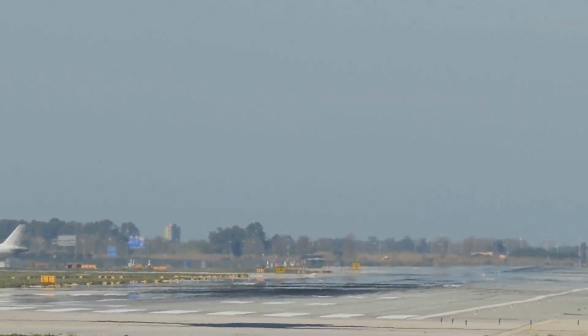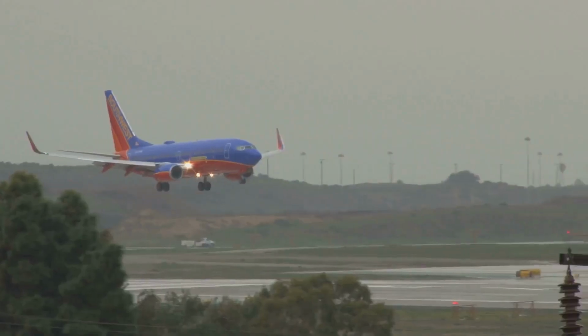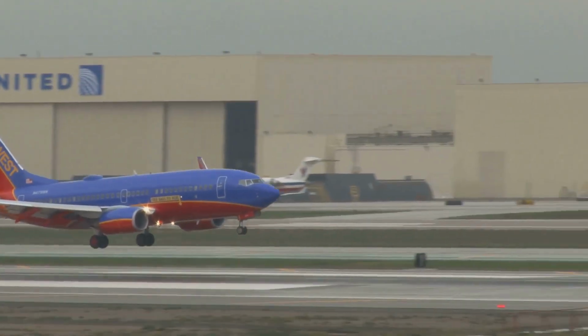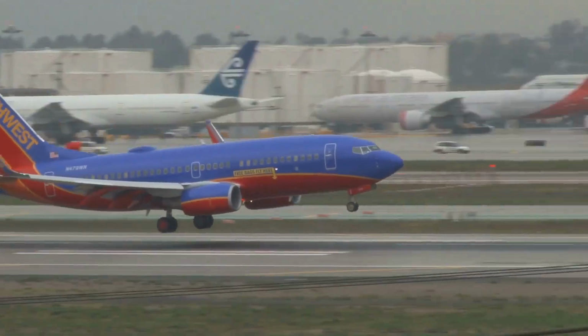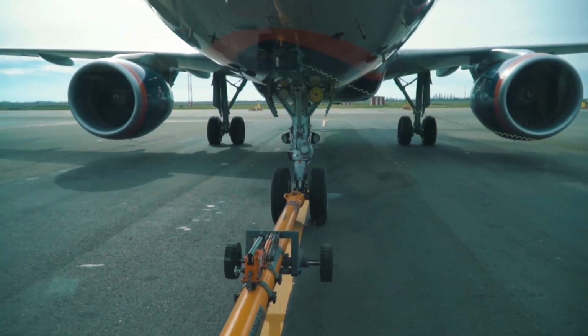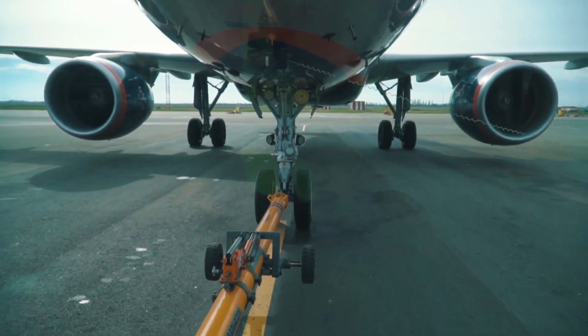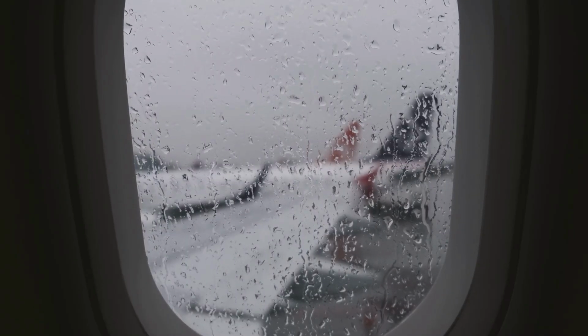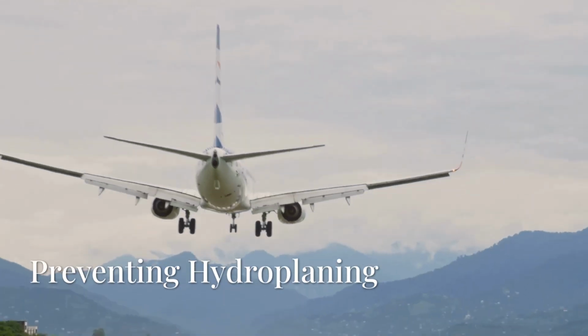Shorter ground roll. In wet conditions, a harder landing can help ensure that the aircraft is firmly on the runway and that the wheels are making better contact with the surface. This can assist in achieving the necessary braking effectiveness sooner.